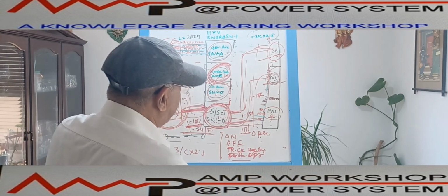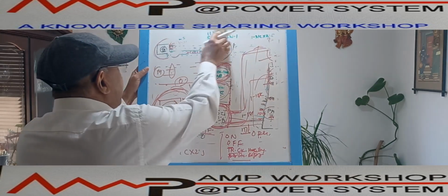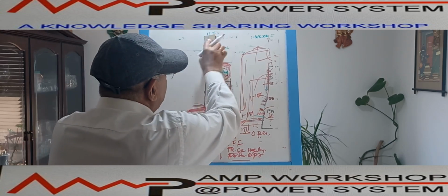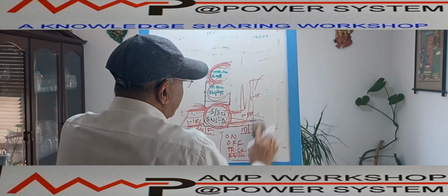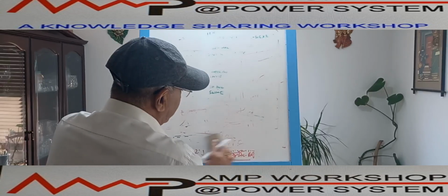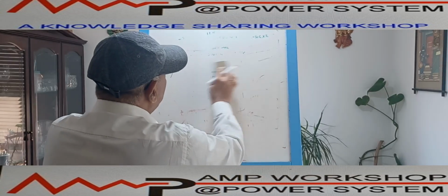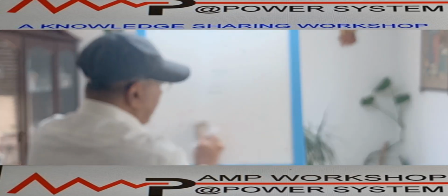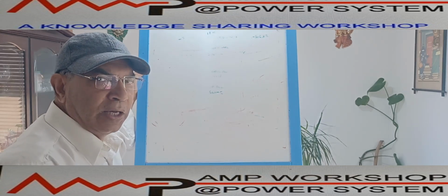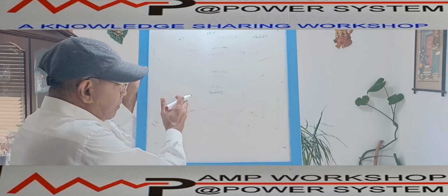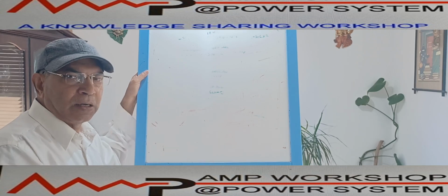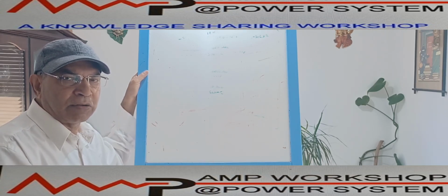So, like in the previous video, finally we can make one table, and from the table, for each type of equipment, we can estimate the amount of cable required for the various types of cable, and then we can multiply that amount by the number of loads we have. From that we can calculate the total amount of cable, and from the designation we can see the arrangement, and the distance also we can see.